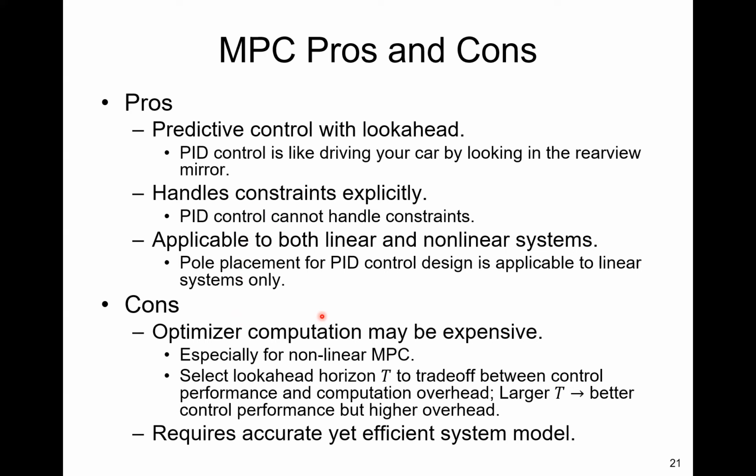MPC was initially developed in the process control industry, that is, in chemical plants, where you are controlling chemical reaction systems, and the look-ahead horizon may be a few hours or even a few days. You're issuing a control command maybe every half day or every 4 hours. So in that sense, MPC is not a real-time algorithm. You can compute it very slowly, solve the optimization problem in an hour. That's still okay for process control.